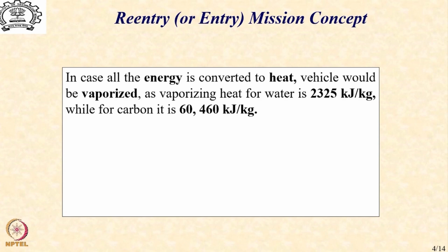You would find that the vehicle actually would get vaporized while entering the atmosphere, because the vaporizing heat for water is only 2300 kilojoules per kg, whereas even from the mission which is from a low Earth orbit of 322 kilometers, the total energy content is of the order of 32,000 kilojoules per kg. Similarly, the vaporizing heat for carbon is 60,460 kilojoules per kg.